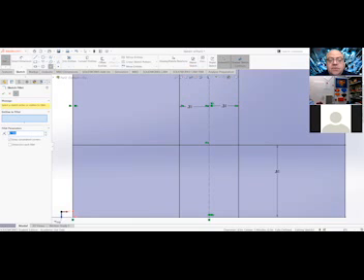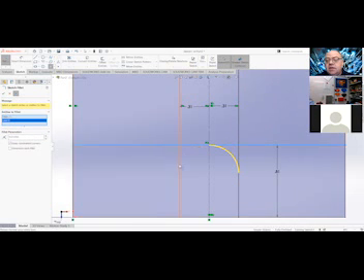It's going to ask you for a radius. The default is 0.1, whereas in AutoCAD, the default is 0. So go ahead and put in 0.3125. Make sure you get that decimal in there. And that will help a lot. Then when they come back over to our part, I'm going to select the horizontal line and a vertical line, and the horizontal line and a vertical line.